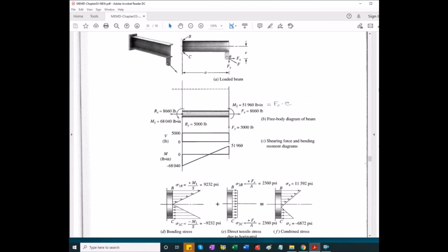Static equilibrium gives us reactions at the encastration, and with it we can draw a shear force and bending moment diagram, and see the bending moment diagram ends, since we have a concentrated moment at the end of the beam, non-zero. So this would be the value of the moment. And in terms of their effect, leaving aside the axial force, we have maximum bending stress occurring at the encastration.